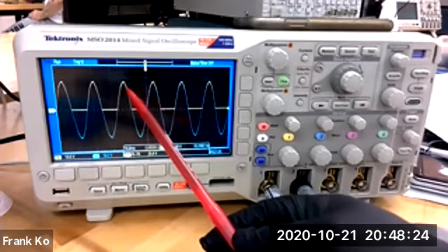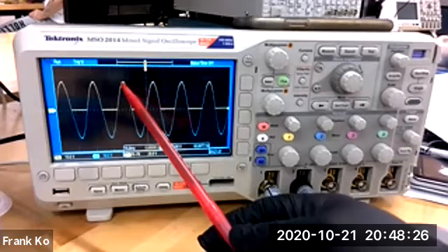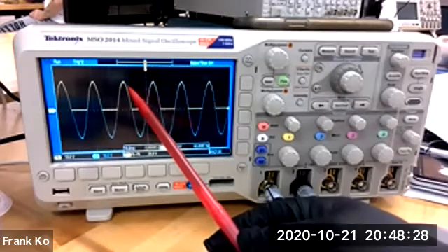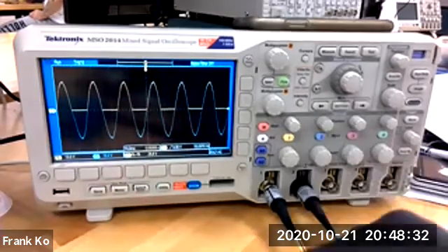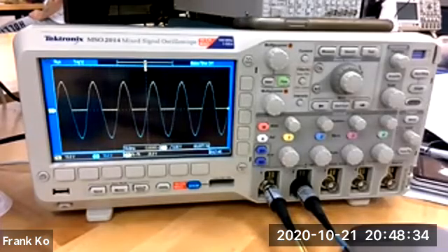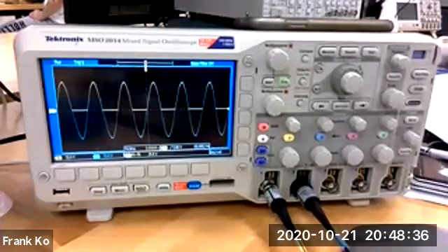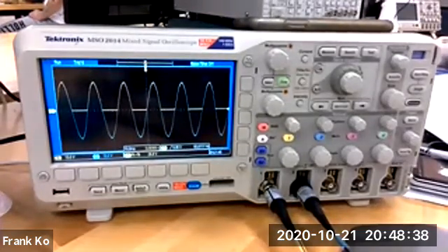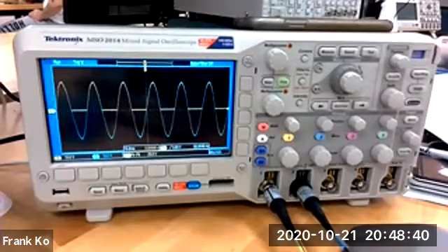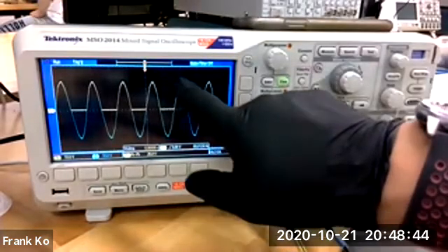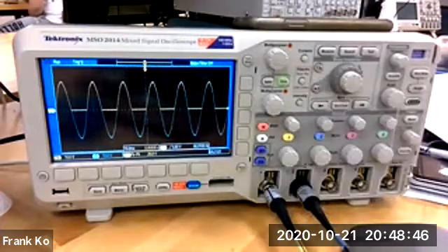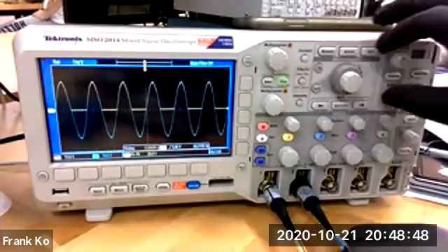If I were to magnify this part of my oscope display so that you can see, there will be a slight difference between the two. And the reason why there's a slight difference is that in order for the diode to work, it takes about 0.6 volts or 0.65 volts to turn on that diode. We can't see that slight difference lost in this particular scale of the oscope display.